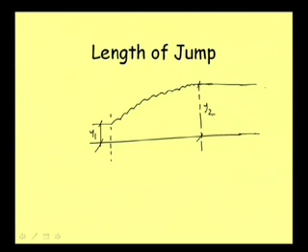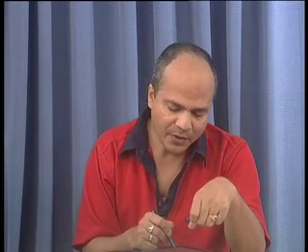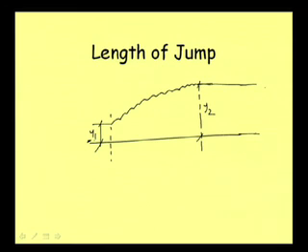And another technique we can use here, rather than only observing, is this. Finding y1 is comparatively easier in practical experimentation. Once this y1 is found, then if it is a free jump, or even if it is not a free jump, suppose it is a repelled jump, we will know where it is starting.